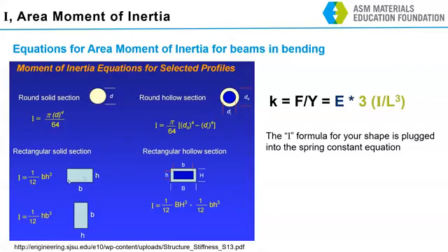Okay, here's our diving board. So this term in our equation, this big capital letter I, our area moment of inertia, is given by this formula here. So the stiffness of the beam is going to be related to the width of the beam times the height cubed. Okay? So in the case where we have our diving board orientation, B, the width of the beam is larger than my height.